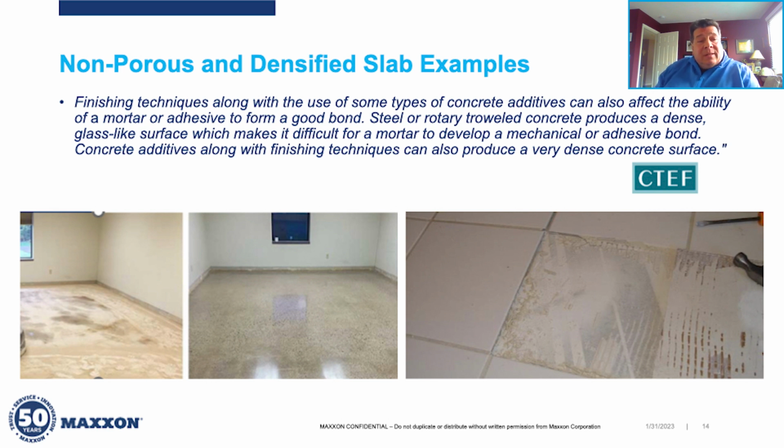And I took this verbiage from the Ceramic Tile Education Foundation, where you see there, it says finishing techniques along with the use of some types of concrete additives can also affect the ability of a mortar or adhesive to form a good bond. Steel or rotary troweled concrete produces a dense glass-like surface, which makes it difficult for a mortar to develop a mechanical or adhesive bond. So that's basically what we're going to be talking about in this next section.